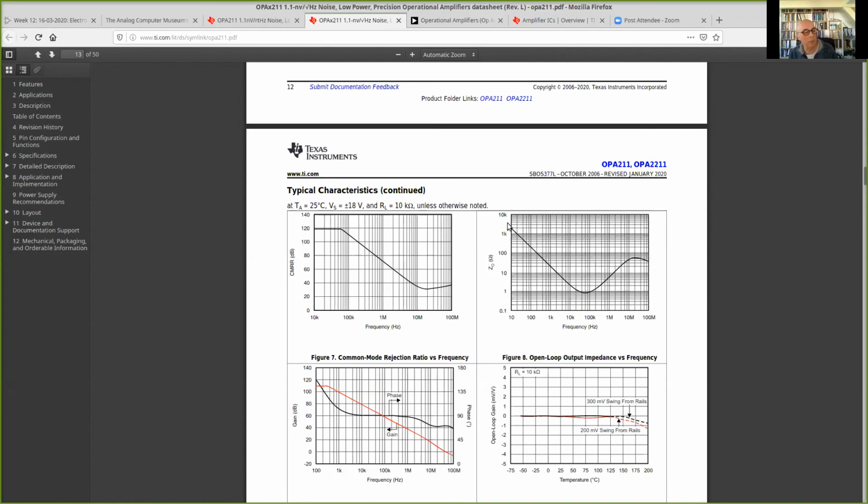If I put it here, well, then I can usually use only this model, or if it is a very large capacitor. So in this range, a capacitive load looks dangerous if I only consider the output impedance. So it's not simple to answer. Usually take 10 times more than the bandwidth you need, but it really depends on the specific situation with your load impedance as well.